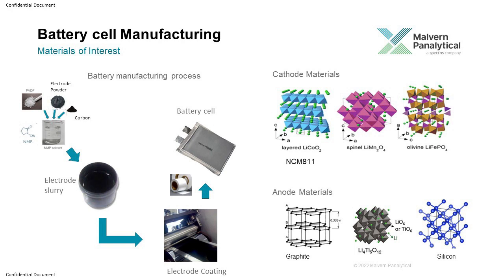The disadvantage is that it has slightly lower energy density compared to NCM. So for the NCM 811, you can reach energy density of 250 kilowatt hour per kg. For the LFP, it is about 150 kilowatt hour per kg. So there is an energy density difference, but it is a very safe chemistry. Many people say that for the environment that exists in Asia, that is more hot kind of climate, maybe LFP is a better chemistry, although it gives slightly lower performance.